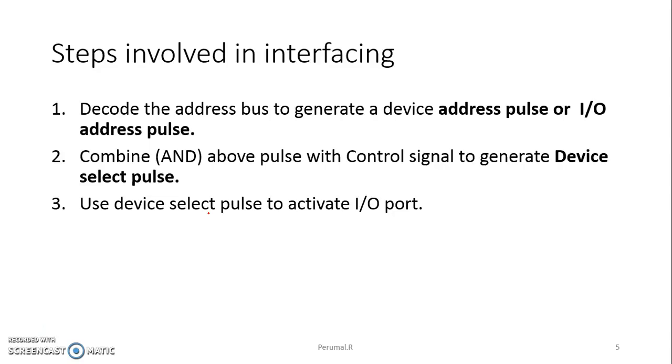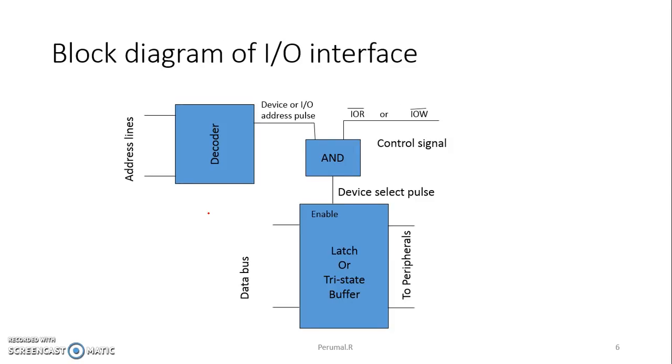The same as what we have studied in the think pair share activity on interfacing with memory, we need three steps: chip select signal and control signal, memory read control signal or memory write control signal. Following that we will get the data on the data bus. The same thing, three steps are followed for interfacing with I/O devices. See the basic block diagram of interfacing with the 8085 microprocessor. See how we will be performing what we have studied in the previous slide.